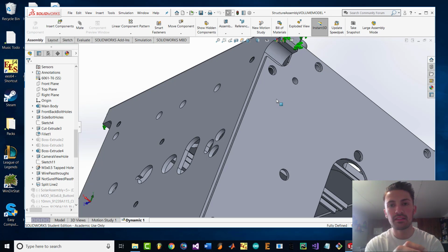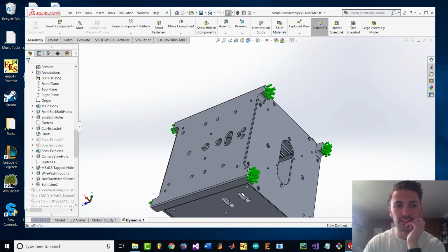So then it's going to throw up the yellow box saying, hey, your constraint isn't defined anymore. As those constraint problems come up, exit out of the part and delete the problem constraint.